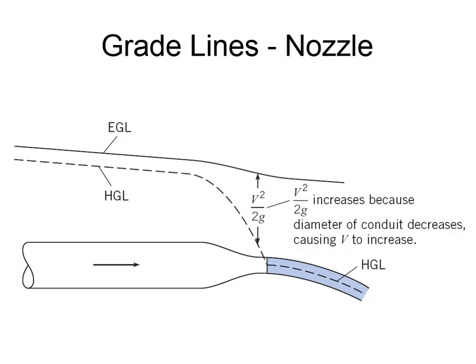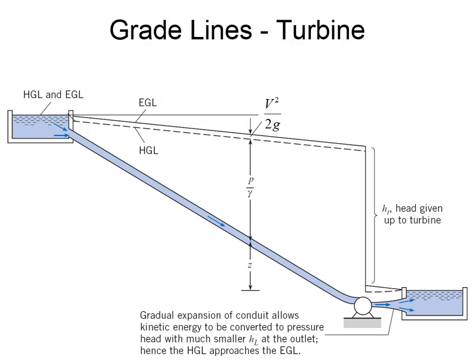Can they control the power, increasing resistance? I think that they do. I think that what they usually have at an actual power plant is that the turbine and the generator are most efficient at a certain number of RPMs, and so they'll have maybe 10 of them, and when the demand is low, they'll only direct flow through maybe a couple of them.